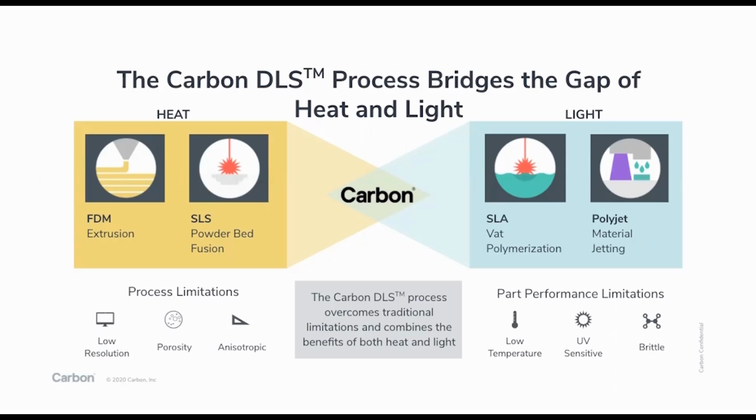On the light-based technology, we're taking a photopolymer and using photochemistry to turn it into a solid where light is applied, either from a DLP system, a digital light projector, or with a dancing laser beam. In the case of vat polymerization, you have to commit a large volume of resin, a photopolymer, and you create your object at the air-liquid interface and pull the part down into it.